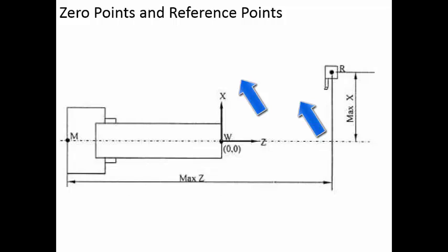By using some simple transformation functions, you are only shifting the points, so you are only doing the transformation, that is translation. By simply adding and subtracting the x and z coordinates, it is able to compute the coordinates of the point in the controller coordinate system or the CNC coordinate system. We will write the program in the workpiece coordinate system, that is the 0 origin we created, but the CNC will understand the motions only in its own coordinate system. So whatever the computations are, all of them will be done by the controller.